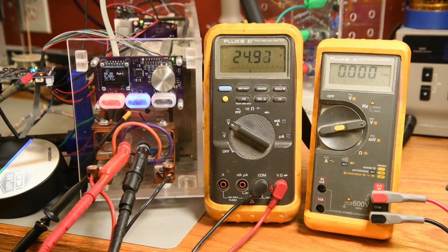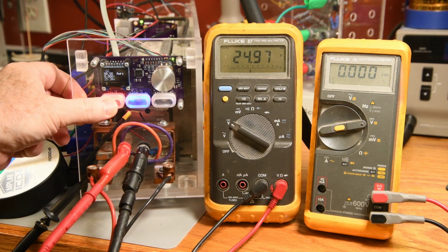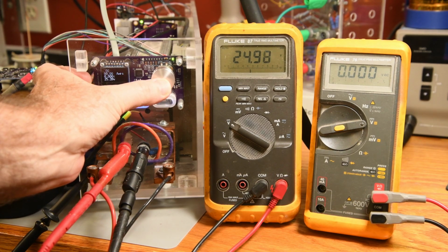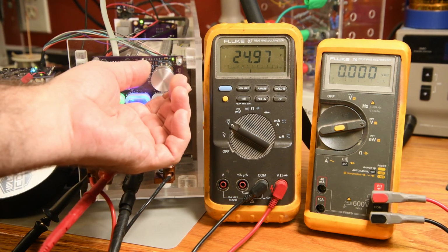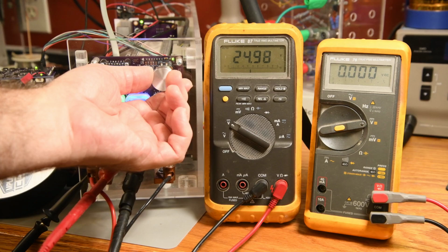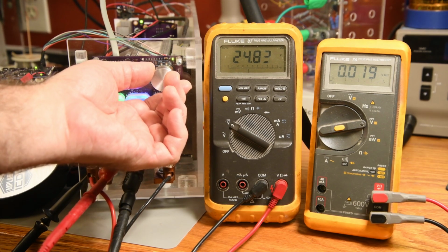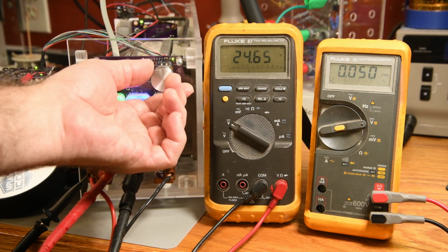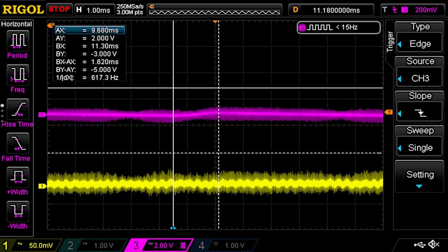With a bit of code in place to read the ADC current values and update the DAC output registers, I've got to give it a spin just to see if things are heading in the proper direction. The load is connected to a 600 watt regular old linear power supply. The meter on the left is reading the voltage at the input of the load, and the meter on the right is reading the voltage from a current sense circuit. Very close to 100 millivolts per amp. I think it reads a bit on the low side. I'll pause here at 600 milliamps.